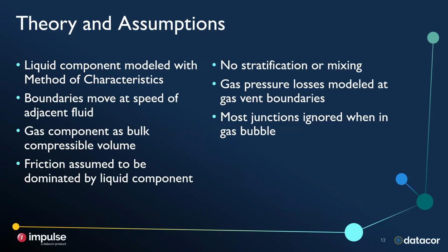And each bubble has to enclose at least one of the stations used for method of characteristics. So the sectioning is going to matter a lot. I would recommend at least 10 sections per pipe, at least for the pipes that the bubble is passing through. There may be dead branches in your system that aren't affected by the bubble that are just used for pressure probes or things like that.